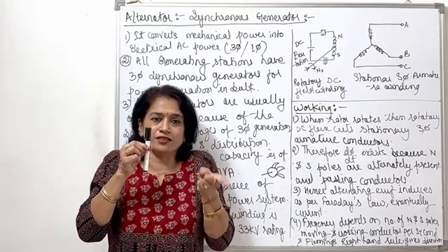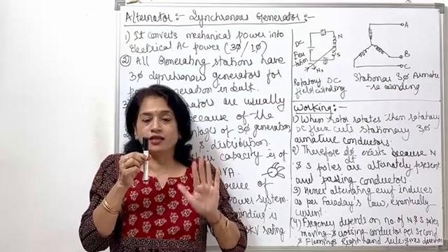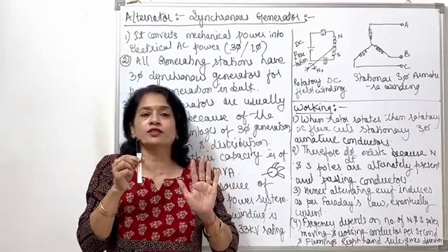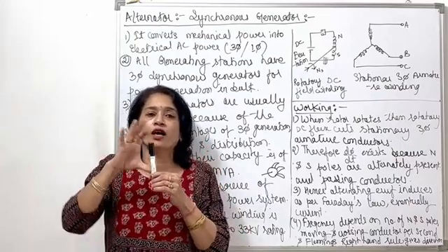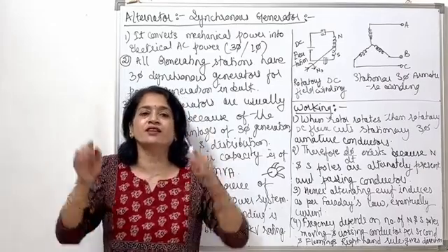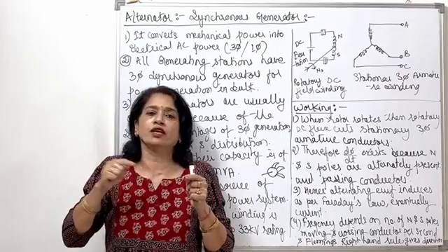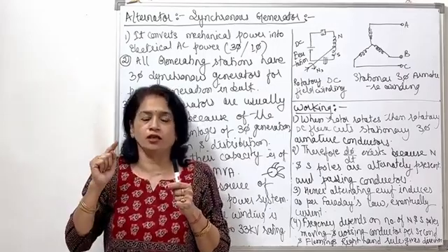First phase is like this, second phase is like this, third phase is like this. But as I said earlier, this is not the actual physical construction. In the physical construction, we have the rotating magnetic field, and outer to it, in a cylindrical, ring-type structure, we have the 3-phase winding in the slots of the stator on the inner periphery.